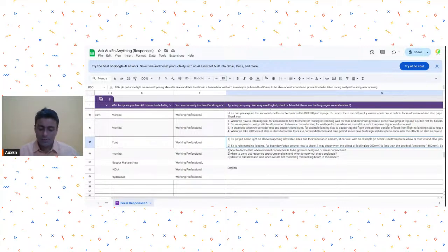When it comes to shear wall, there is a clause given in IS 16700, clause number 8.5.2. You can read that clause, and basically it says, I'm reading it from the code, when the opening size is less than 800 or one third the length of wall in height or length, the influence of opening may not be taken into account in the overall stiffness of the building.